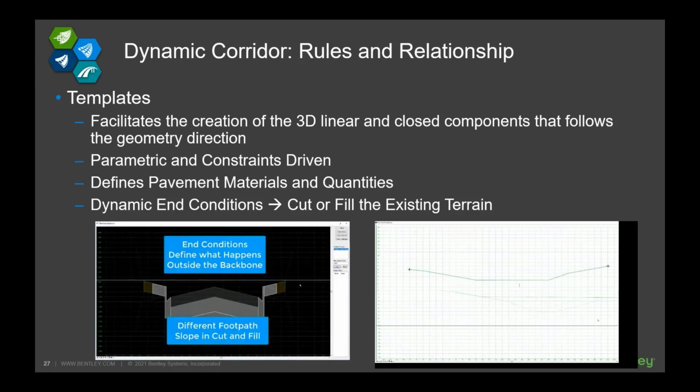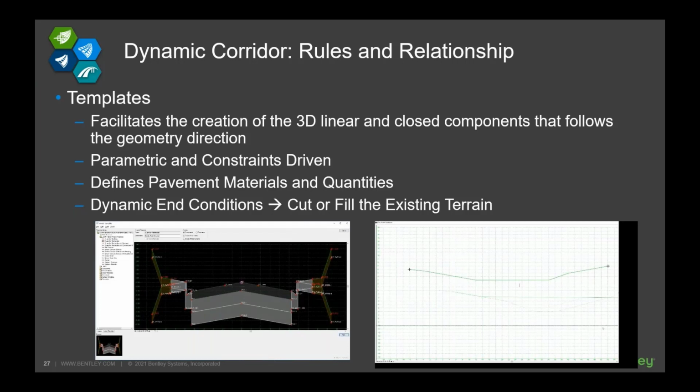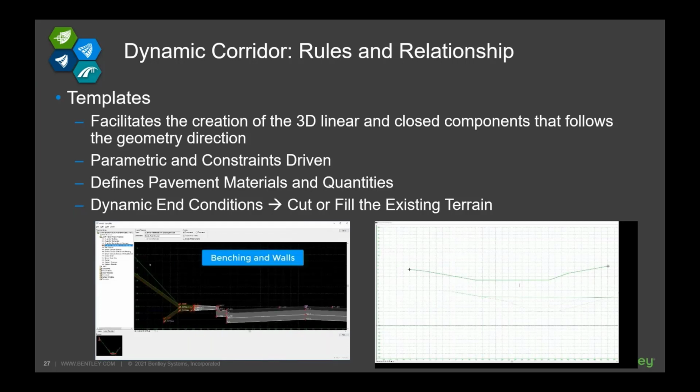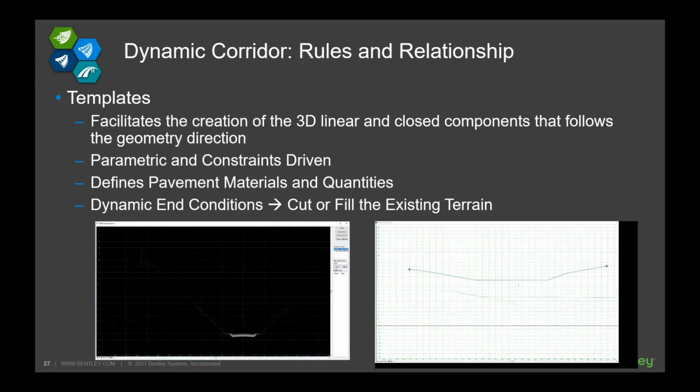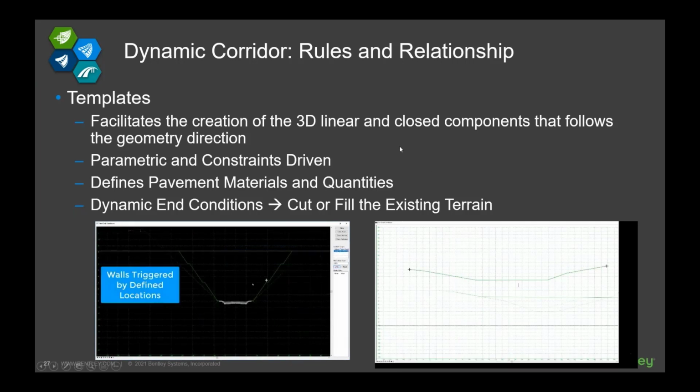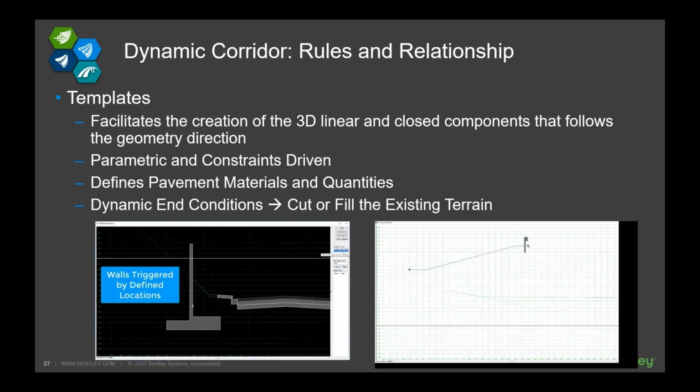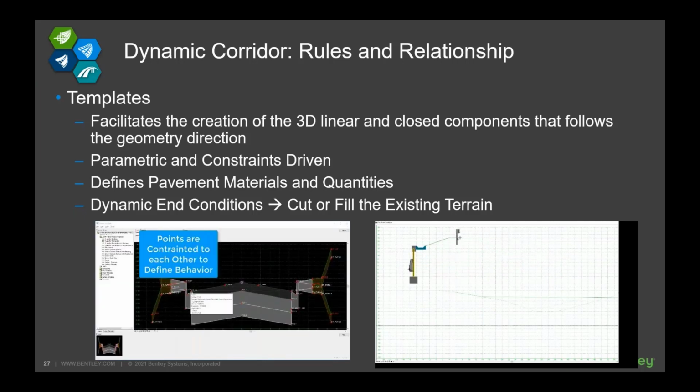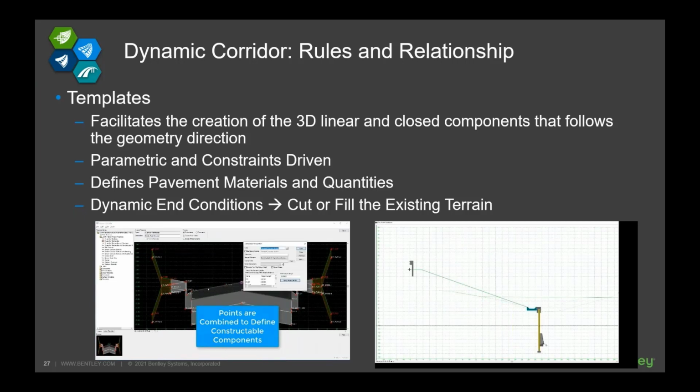Of course, I have to be honest, because the technology behind Civil 3D and ORD are very much different. So the subassemblies or assemblies that you have created in Civil 3D, you have to recreate them and create them into a template. The template, which is basically what you're seeing on the screen, is the equivalent of the assembly and the subassembly in Civil 3D. Did I answer that clearly? So again, just export them into LandXML, then import them inside ORD.